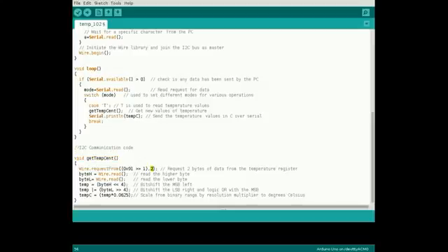First, request 2 bytes from the sensor. A note on this 7-bit address: 4 TMP102 devices may share one I2C bus, and read operations are addressed 72 to 75, based on the ADD0 pin configuration. Since we have grounded it to logic 0, we use decimal 72, which is found by converting the hex number to binary and bit shifting right once.